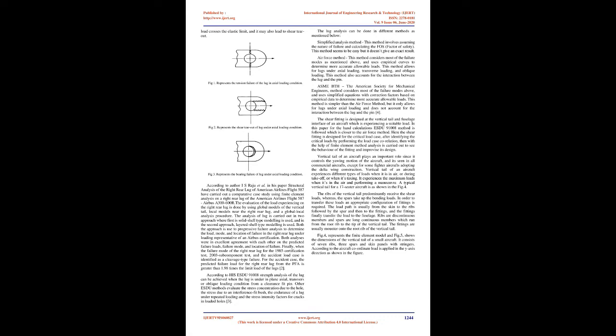The analysis of the lug is carried out in two approaches: in the first, solid shell type modeling is used, and in the second approach, layered shell type modeling is used. Both approaches use progressive failure analysis to determine the load, mode, and location of failure in the right rear lug under loading representative of an Airbus certification. Both analyses were in excellent agreement with each other on the predicted failure loads, failure mode, and location of failure.